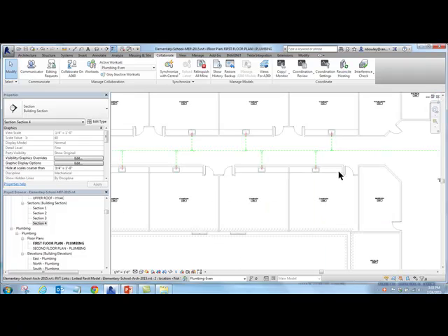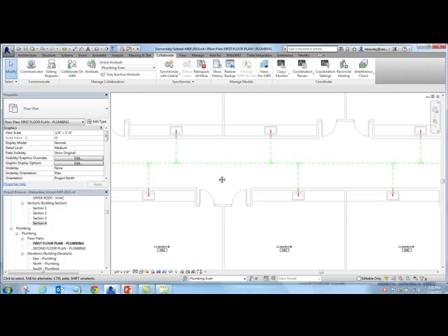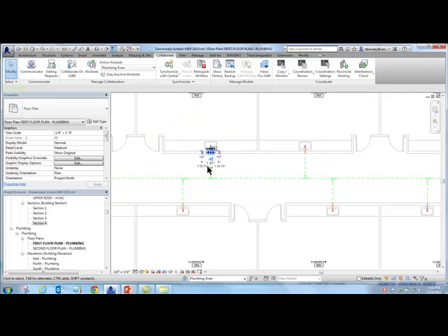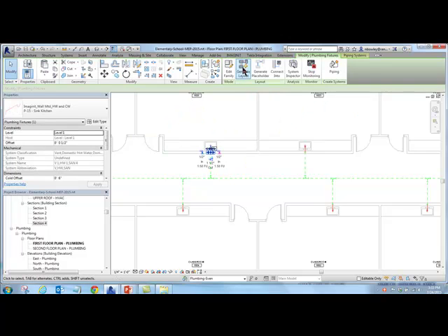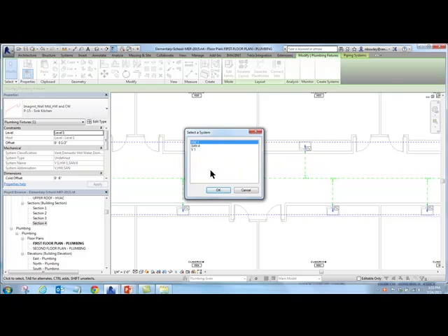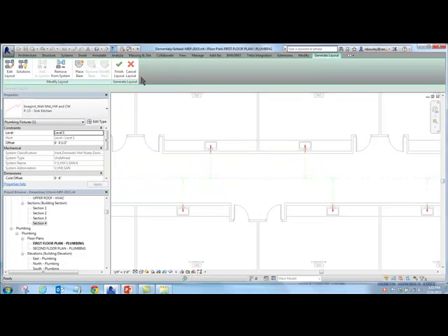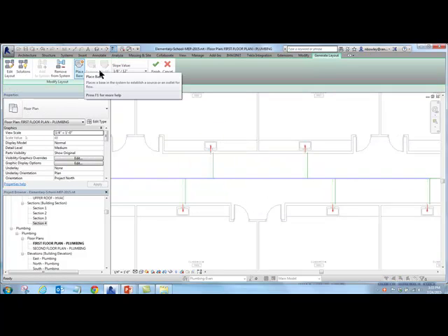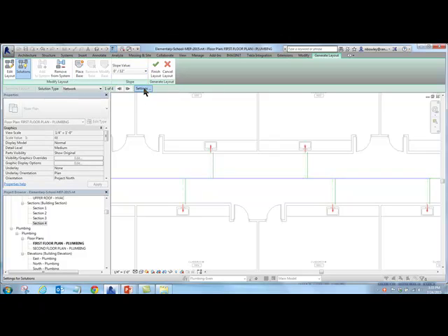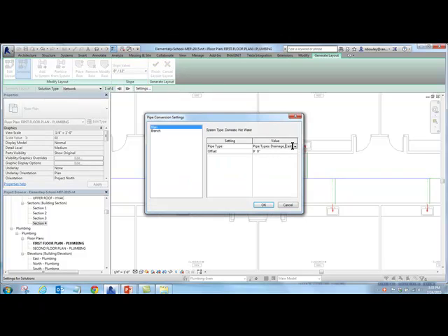I want to talk more about slope piping, but maybe not yet. So let's do another one without it going all weird on me because of the work sets issue. I'll do hot water this time. Let's turn off the slope, go into settings. Where do I want my hot water to go? Well, I want it to be a copper pipe. Maybe I'll put the hot water at 8'6". And then the branch, actually the branch I want to be at 8 feet 6.